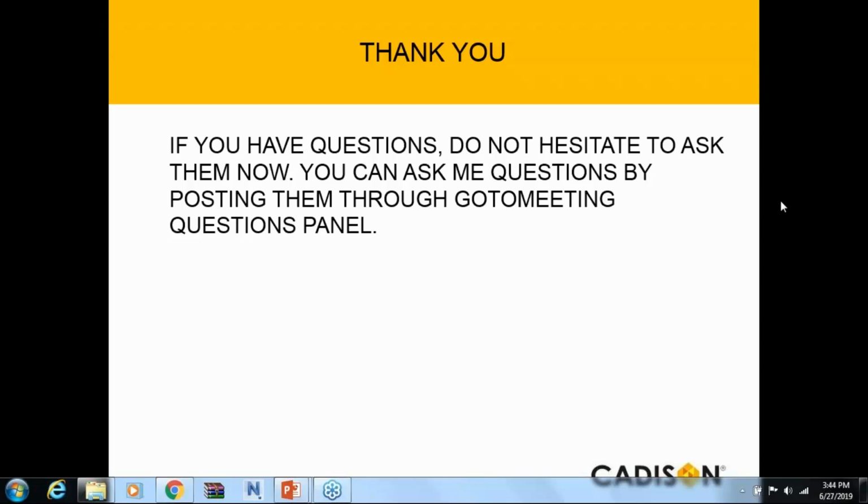Is clash management and reporting available? So yes, we have a clash management in our system, and from this clash manager you can also extract a report. But also, since Navisworks is a universal platform for doing clash detection and reporting, we have also added a Navisworks export in our CADISON 3D designer, so that you can export the model to Navisworks and then do the clash management over there. But yes, within the CADISON system it also exists. We can give you more information about this since you asked this question.